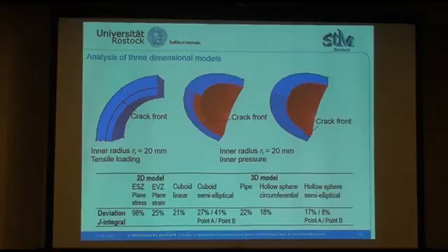In this table you can see the deviations of the J integral between both material models, where the base value is the J integral of the Numerical model. Most of the deviations are about 20%, which means that the J integral of the Chaboche model is about 20% higher than the J integral of the Numerical model. As you can see, there are also some deviations between the points A and B, but the most eye-catching deviation is this one.